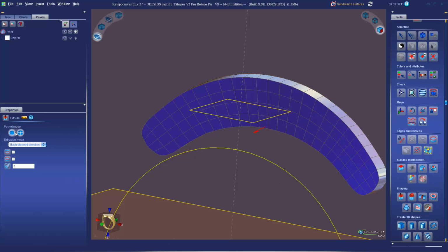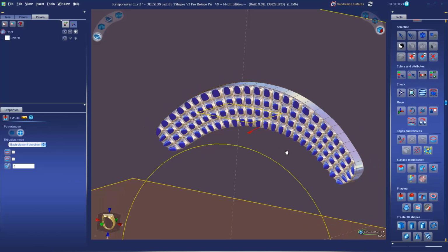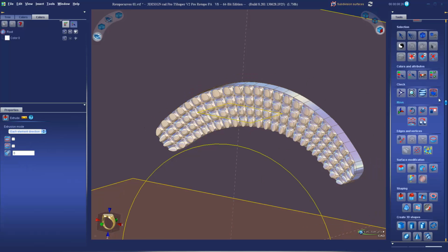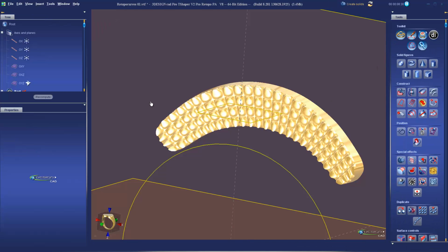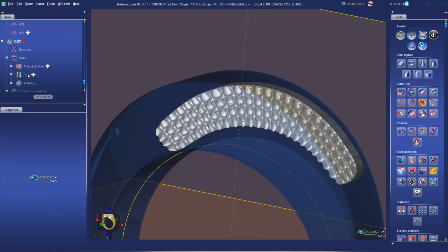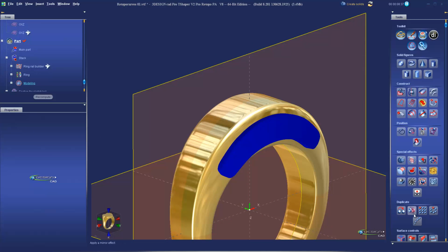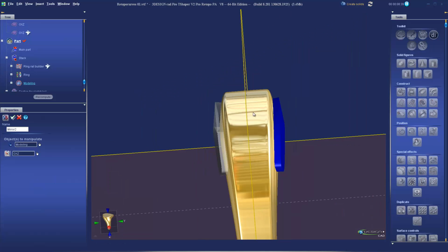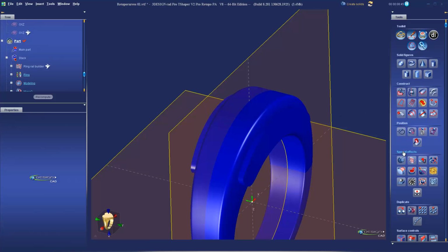We'll do an extrude. This time we'll do a pocket mode in split so that each square will extrude separately. And just give a little tug on that to extrude it out, however deep we want our piece to go. And once again, we'll exit out to 3D design, find our ring and re-show that, and then do a simple mirror so we can copy it on both sides if we want, and then a simple Boolean subtract.